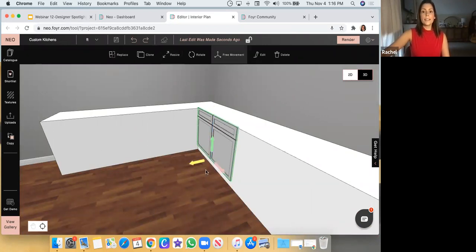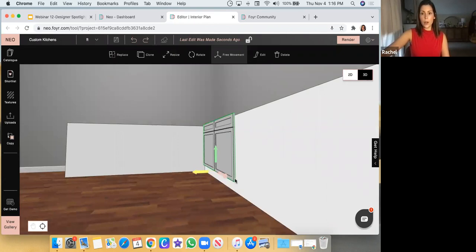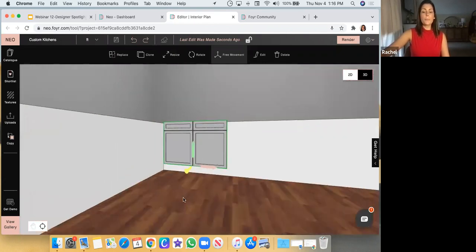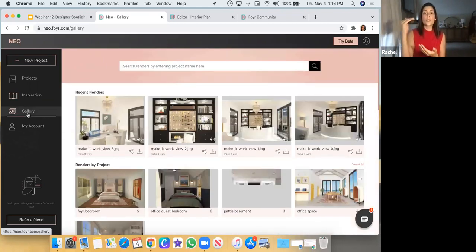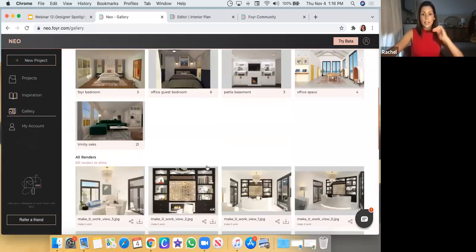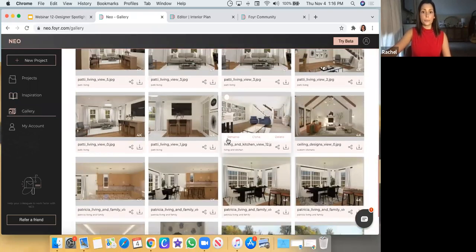And because we don't have a ton of depth here, right? We've got maybe 1 inch for that shutter, but because your lighting is up top, casting down, let me see if I can show you an example. That shadow that's created just from that 1-inch lip is going to create the illusion of more depth than there actually is. So you're going to have that illusion of like an inset toe kick.